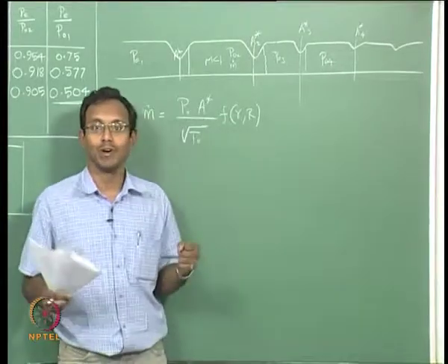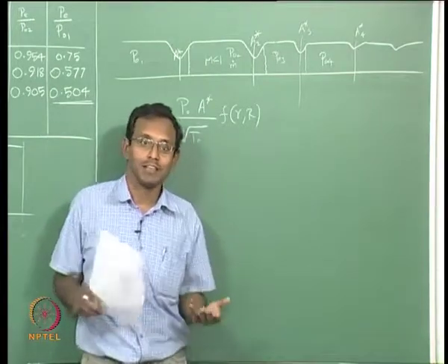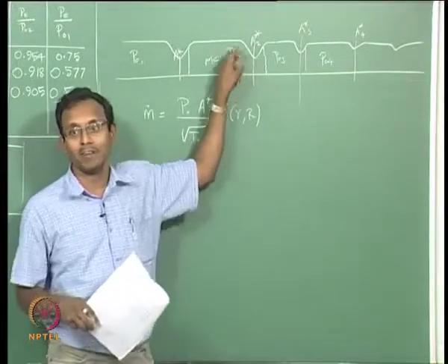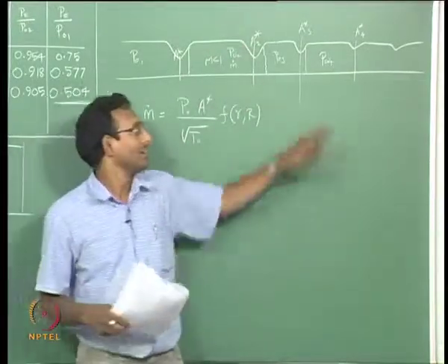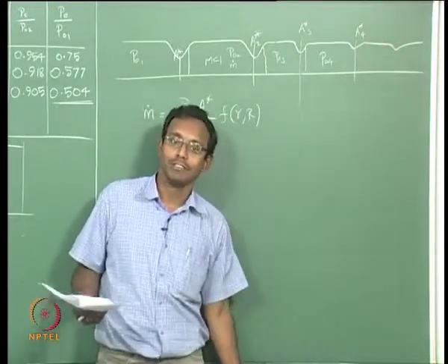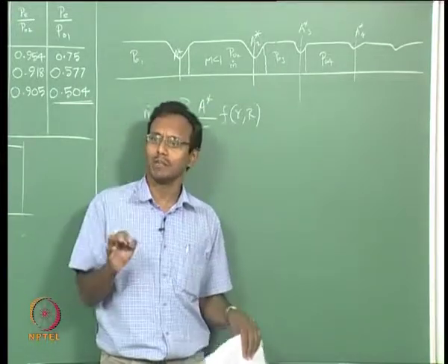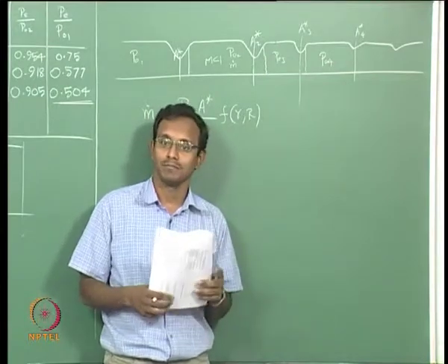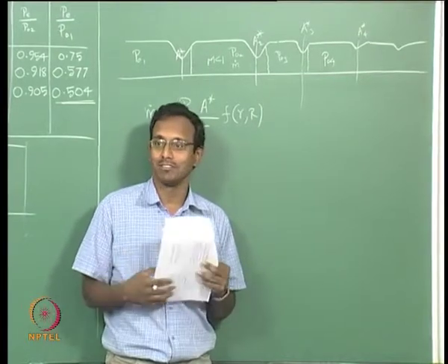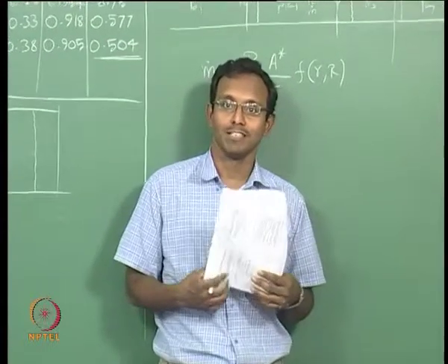because flow has to do work against friction. So my flow energy, the pressure energy is decreasing. If my pressure energy is decreasing, then it cannot go through that small area, it may need more area. There will be a point where that area will be equal to the duct area, and even the duct will get choked. That will be your limit. So it cannot be infinite numbers, there will be a specific number for a given P01. That can also happen. So typically you can choke flow 5 or 6 times, but it could be infinity if you assume no friction. That is where you will be.